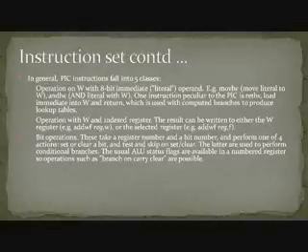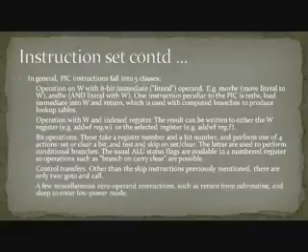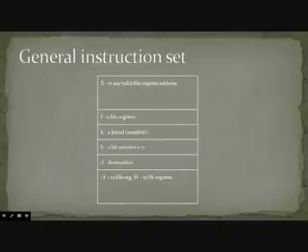The usual ALU status flags are available in a numbered register, so operations such as branch on carry clear are possible. Fourth, control transfers. Other than the skip instructions previously mentioned, there are only 2: goto and call. Fifth, a few miscellaneous zero operand instructions such as return from subroutine and sleep to enter low power mode. These are the commonly used assembly language instructions.